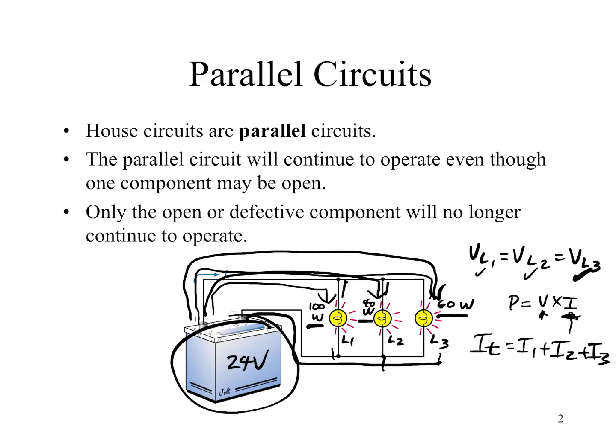An example of a series connection where there is not this independent control would be those old Christmas lights, where if one of the lights in the string were to burn open or go open circuit, all the rest would be disabled. You'd have no light on the whole string until you found the open circuit bulb and replaced it such that there was continuity in the series loop. You can see how inconvenient that is. You can see how it's not practical.